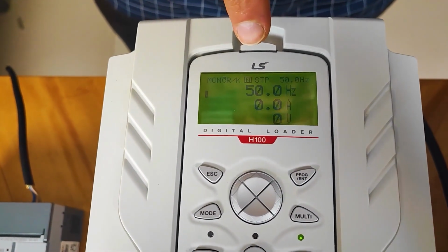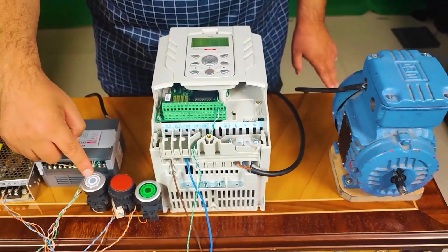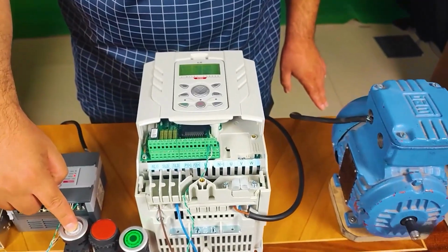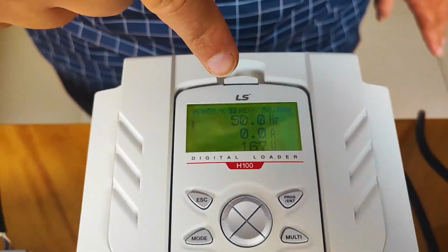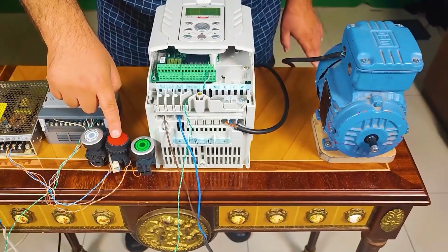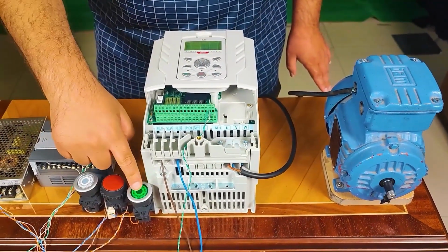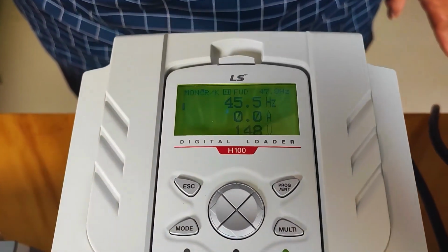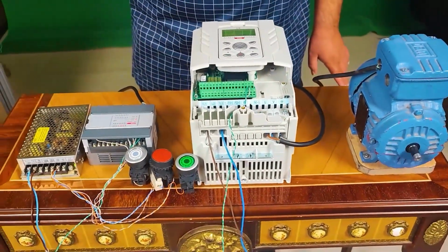Now let's test the program together and see how it works. As you can see, we set the frequency to 50, which appeared on our drive. Now we want to give a command to our drive through these contacts. See, the first contact is reverse, so our drive is working in reverse mode. Our frequency has reached 50. Here I stop, we see that it has stopped, and this is what is related to forward. Look, it's working in forward mode now, and if I try to restart it, our drive will stop.